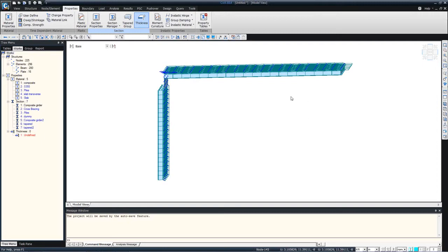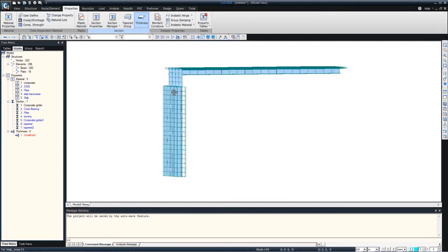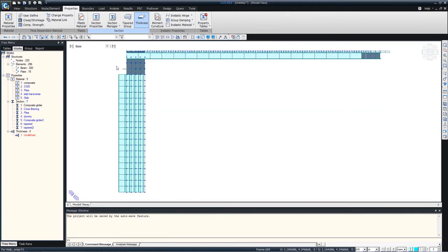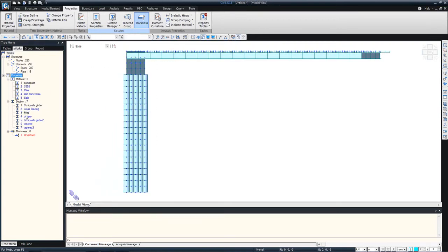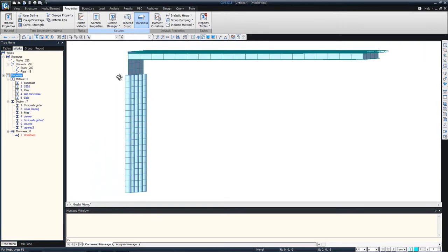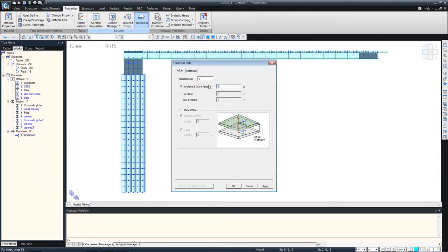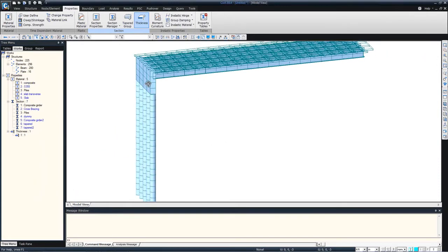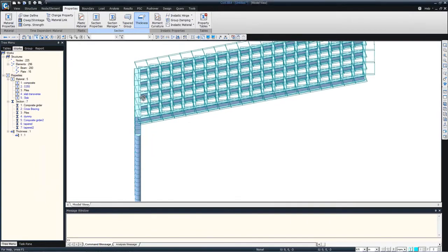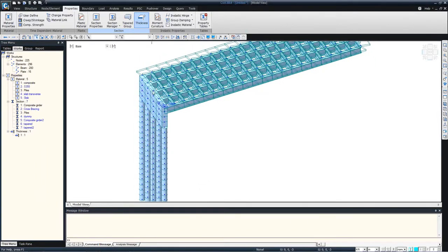Okay, I will now go towards assigning the properties correctly, because everything has been assigned the composite section. Here we just have to select the correct elements, drag and drop piles, double click on piles again, drag and drop piles materials. Similarly for abutment, make sure that everything is abutment material. I haven't defined any thickness for the abutment, so I'll just define 1 meter as a thickness, and that's how we define the abutment and define the sections and the materials.